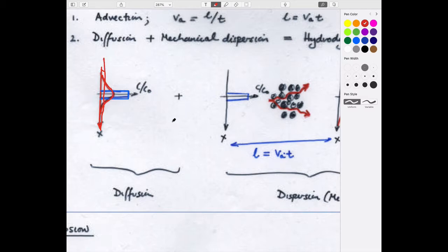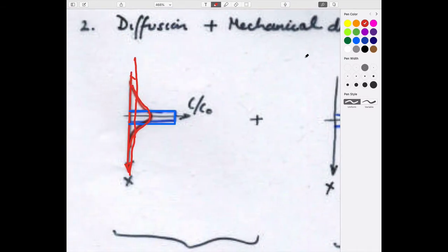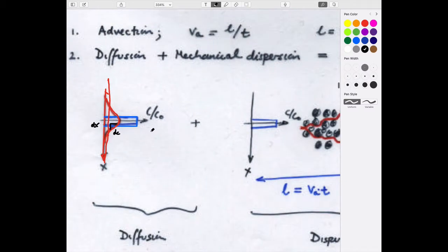And that's the process of diffusion. And physically, really what it's doing is it's taking this gradient of concentration, which you see here, which if I draw this, which would be dc in this direction and dx in this direction. And it's that gradient that is driving the diffusion through Fick's law, which we'll talk about. And so that's a mechanism that occurs just due to molecular diffusion.